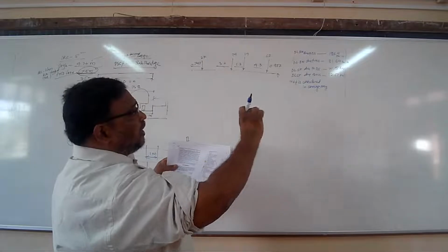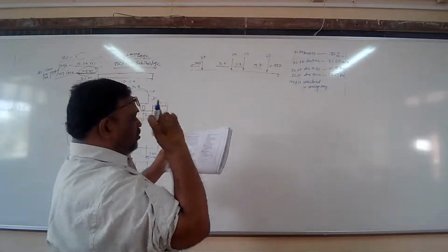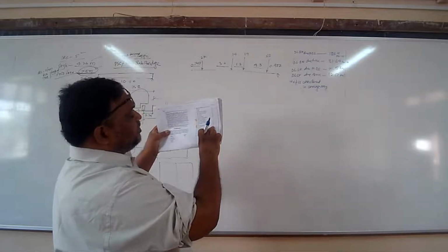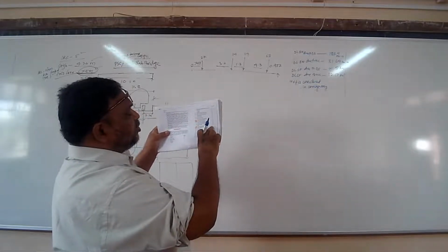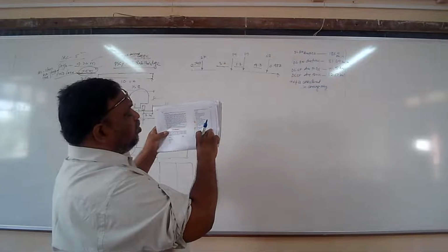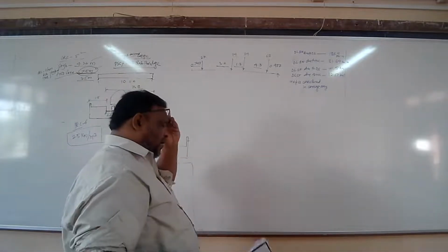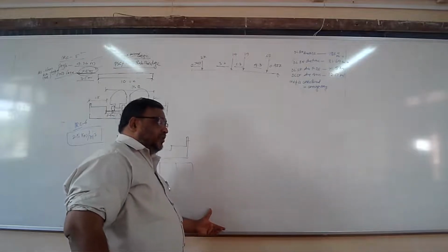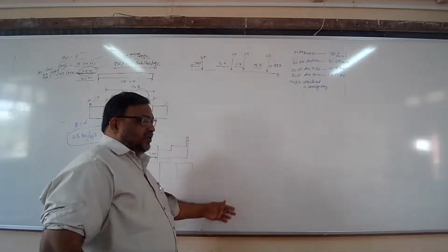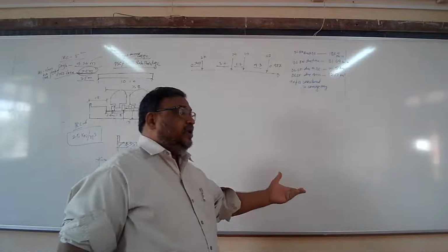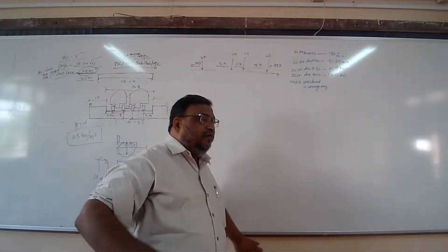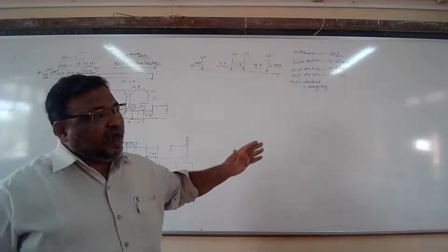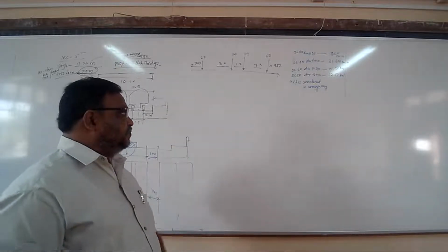Now for the bearing coat, subject to what kind of binder it is, it is 2.2 to 2.6 ton per meter cube. So that is 22 kilonewton per meter cube to 26 kilonewton per meter cube. Any value can be assumed. I assumed it on the higher side, 26. हम 22 भी assume कर सकते थे. या अगर आप कोई दूसरा मटेरियल यूज कर रहे हैं जिसका यूनिट वेट ये कोड में नहीं दिया है, so you must know the exact unit weight of that, and that is to be used in the calculation.